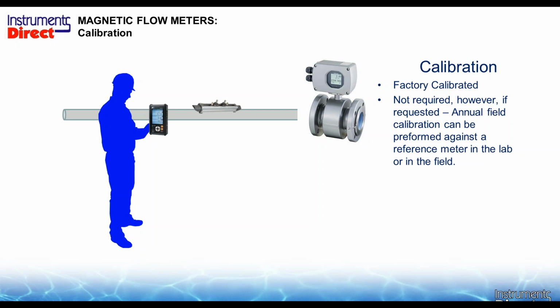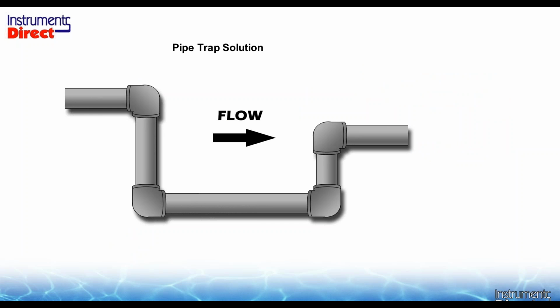A lot of people use non-contact technology, ultrasonic and Doppler, to validate the inline flow meters for annual calibration purposes. The other alternative is to yank it out of line and send it into a calibration lab. In most cases, people don't yank it out of line. You bring somebody to the meter, and there are tools in the market to test the calibration and recertify the device.